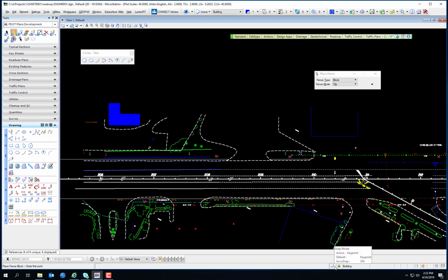Also available is a locks toolbox, which allows users to turn locks on and off. Clicking the tool has the same effect as selecting the checkboxes in the locks dialog, and it can be accessed from the MicroStation menu under Settings, Locks, Toggles, or the status bar locks pop-up menu option Toggles. This may be beneficial when constantly switching back and forth between multiple lock settings. So here you are, and toggles.